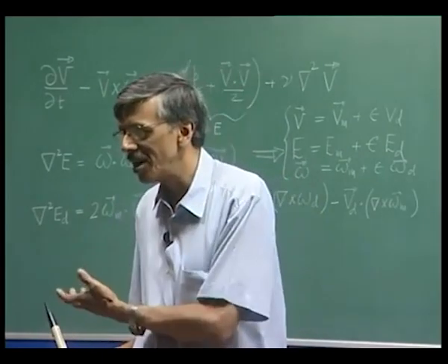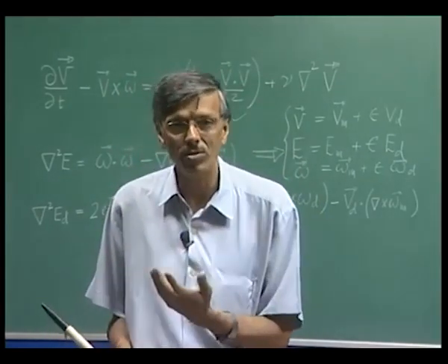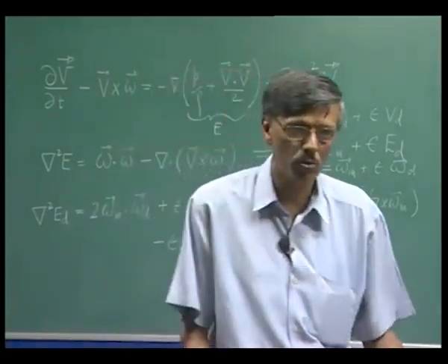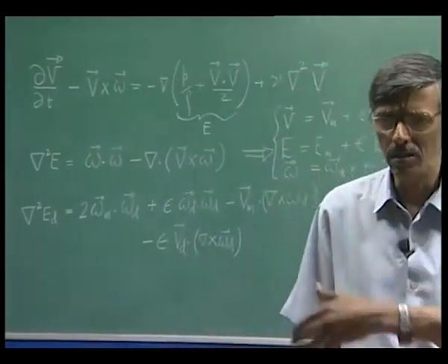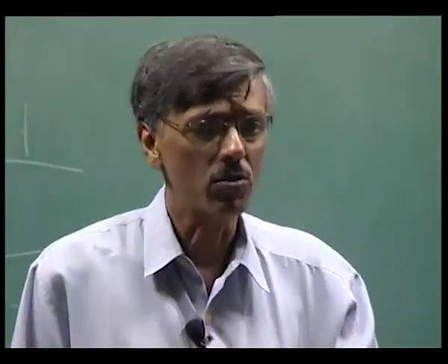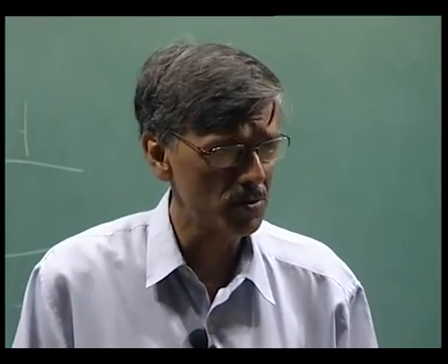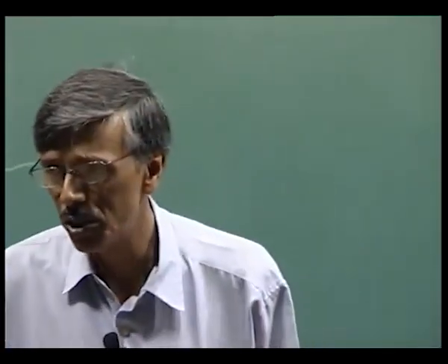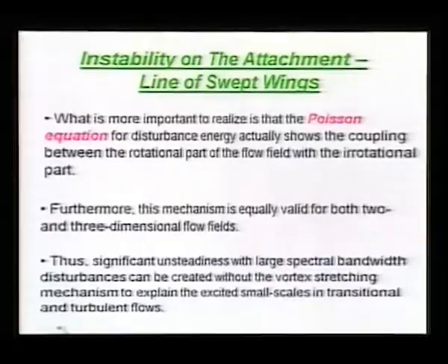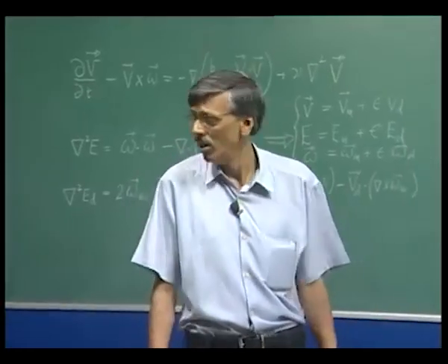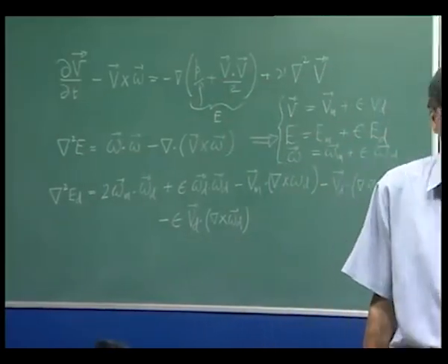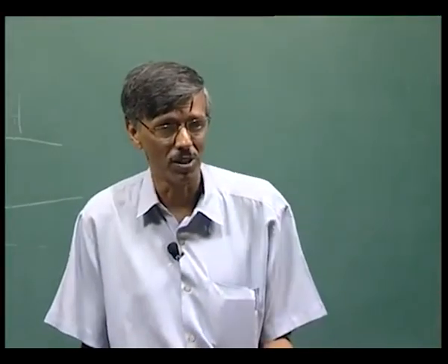see it in the flow visualization that the disturbance field is 2-dimensional, because we saw the dye filament were lifted up in its own plane. So, it remained two-dimensional, the mean flow. The disturbance field at onset was two-dimensional. Later on there was a lateral spreading. So, three-dimensionality would come in, but the beginning of the thing could be very much true for a two-dimensional flow field, right. That was also explained in terms of our numerical results, which was based on 2D formulation, right.